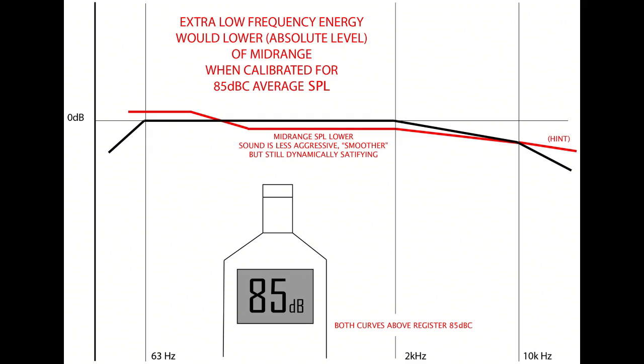That's right. So two things happen. One is the mid-range at reference level will be, on an absolute basis, lower, right? So it's not going to seem as loud to us. It's going to be a few dB less loud. And then the other thing is when you get more mid-bass and low-frequency energy into the spectrum, psychoacoustically, it de-emphasizes the mid-range.